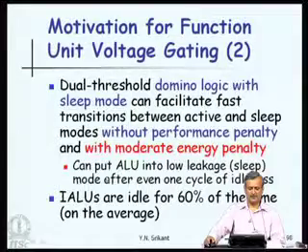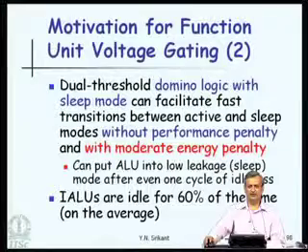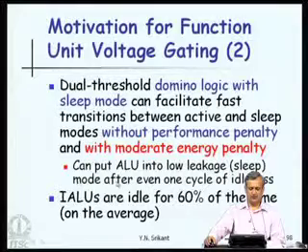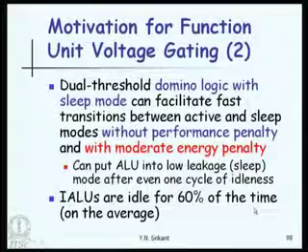Now, the problem is if the switch requires a fair amount of energy, then is it useful to put the CPU in sleep mode very frequently? Obviously not. So, the one cycle of idleness is all that we require to put it into low leakage mode, and we also know the factor that motivates us: integer ALUs are known to be idle for 60% of the time on the average. That is, the integer ALUs do very little for 60% of the time in general.